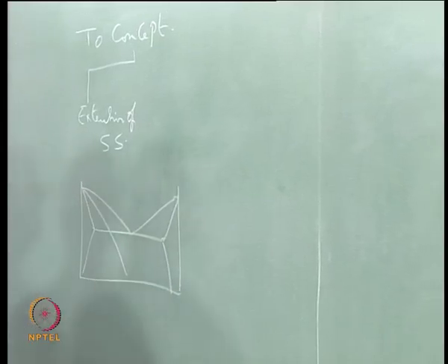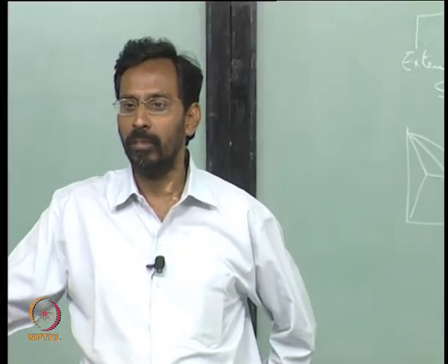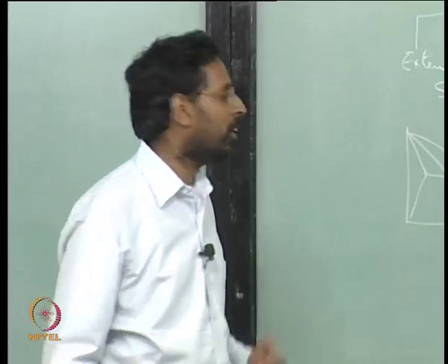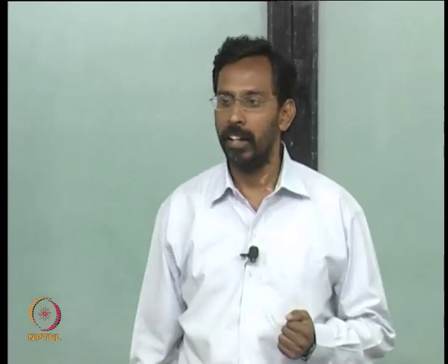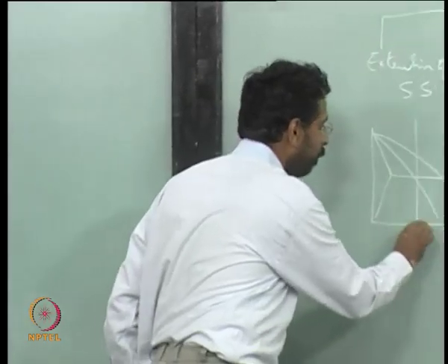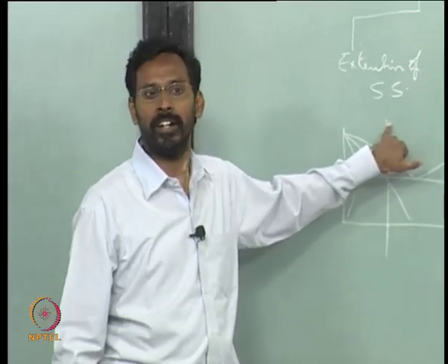T naught and choose a composition of this sort and can bring the liquid below the T naught in such a way that I take care of even the temperature rise during recalescence, that if I can undercool the liquid sufficiently so that it can undergo what is called partitionless solidification, then I have an alloy here which has the same composition as the liquid with which I started, and this is a single phase solid solution now.